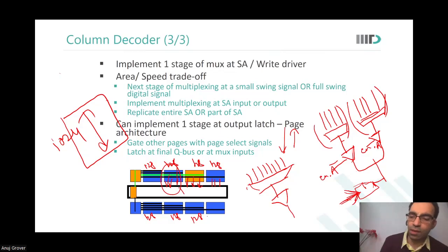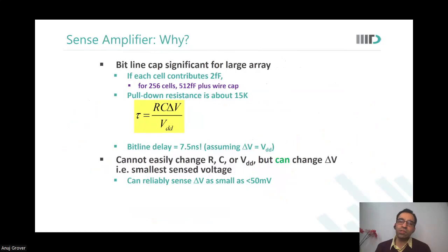Okay. Now we come to the sense amplifier. All of us know there is a sense amplifier in the memory, but why is there a sense amplifier? To sense fast, to improve my read time, because otherwise I have to discharge the bit lines to full 0, or at least VDD by 2 to read a 0.